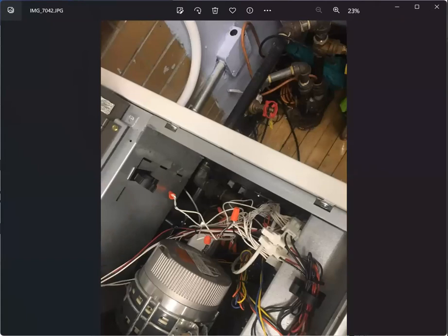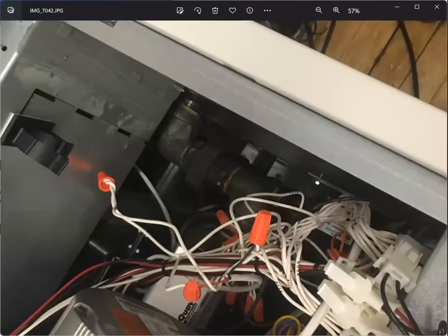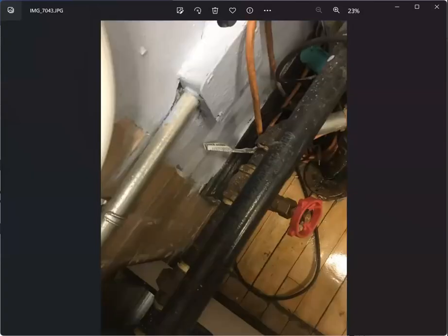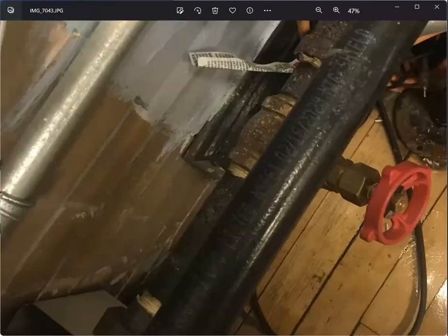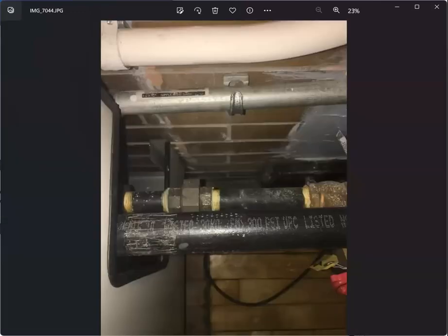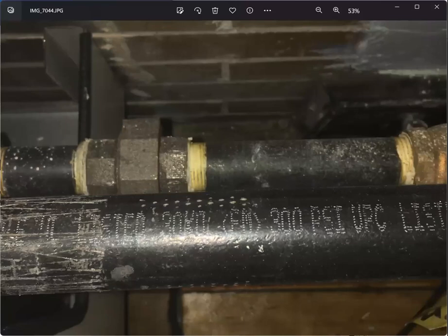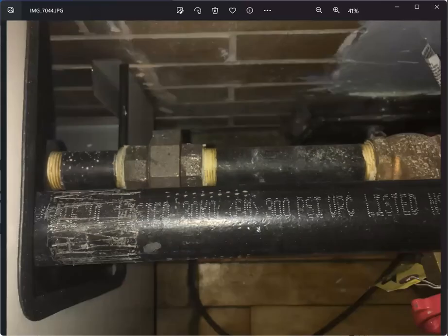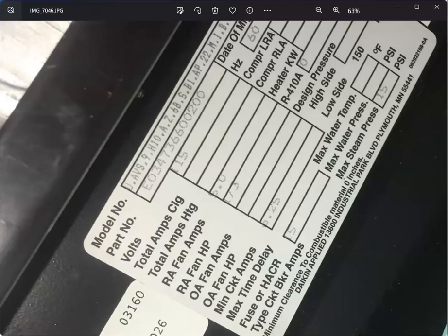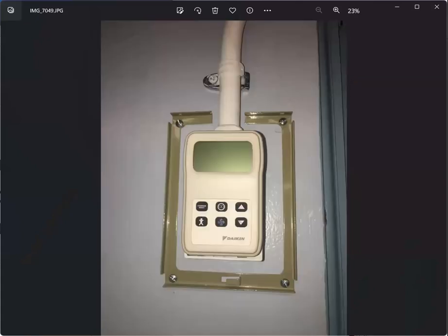This is the assembly of the unit. I just took a photo of this to confirm the connection inside. And this is the piping material label. It says 300 PSI. So at least take a photo of it, take a note, and review the drawing to see if it's according to the drawing. And this is another name tag, H10, which means 1000 CFM.